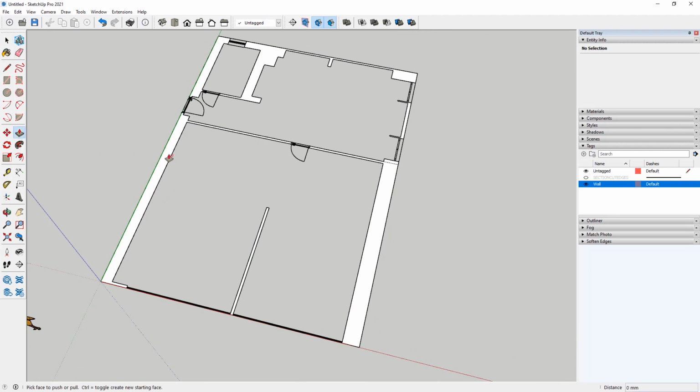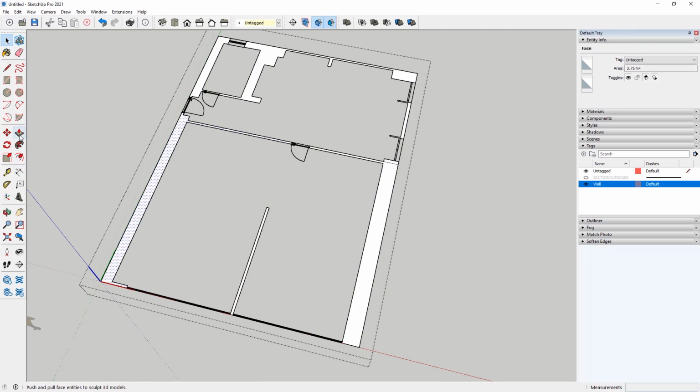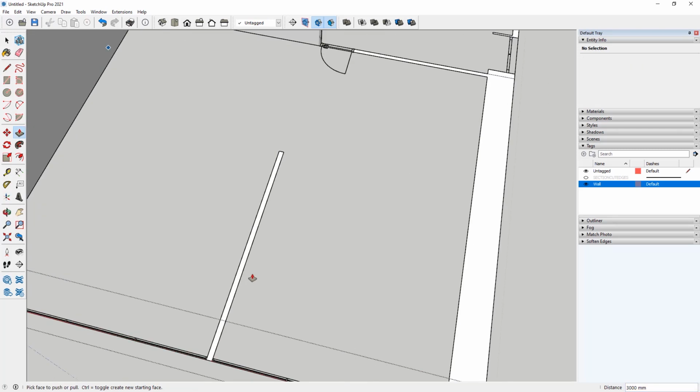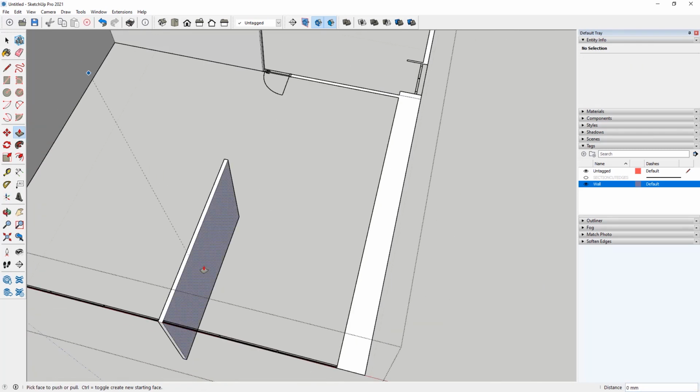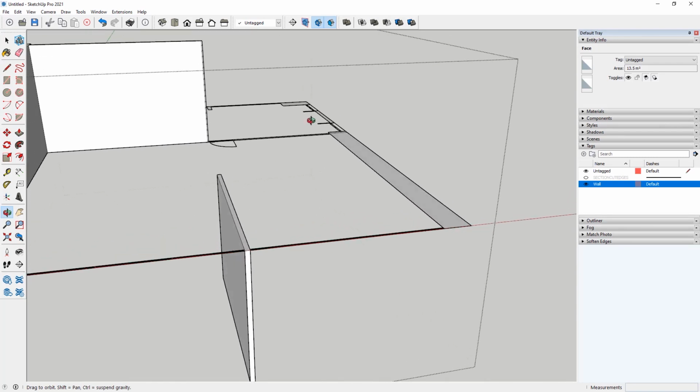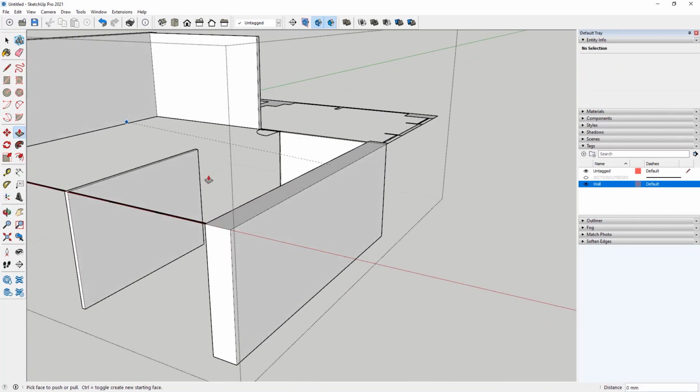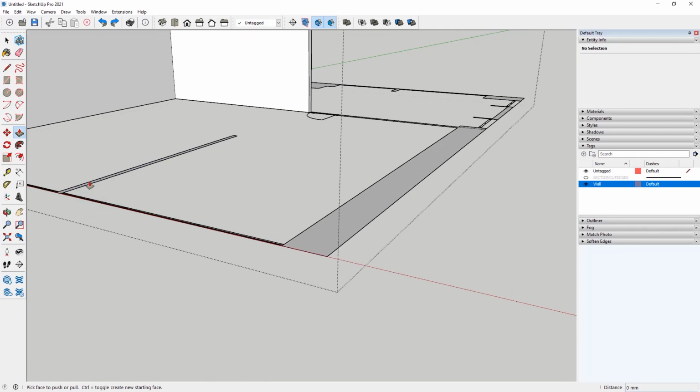If we have finally finished with all the surfaces, now we can use the extrude tool to extrude the walls for some distance. Right now it will be 3 meters, which means 3000 millimeters. Of course, with a double click you will notice that some of the surfaces will be extruded in the opposite direction.